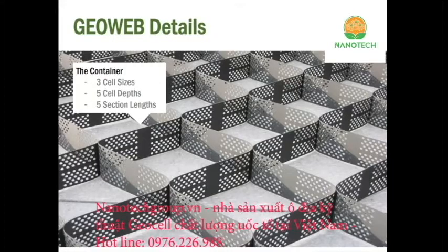consists of two main dimensions. These dimensions are going to depend on your project details and your loading requirements. There are also 5 section lengths to best fit your project needs. The ultrasonically welded seam, where all of the connecting points are, is very important to the function of the geocell. The stronger the seam strength, the better the performance of the geocell. A strong seam allows for a heavier infill material, steeper and taller slopes, and better lifetime performance.